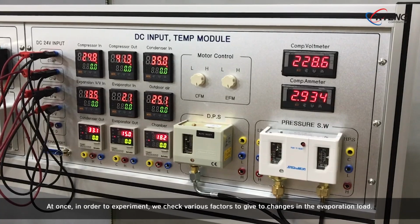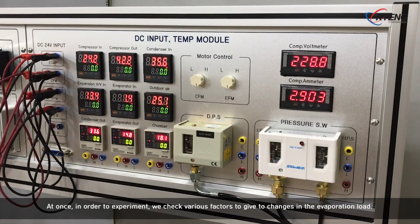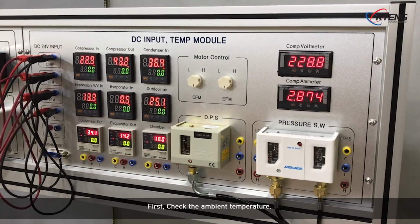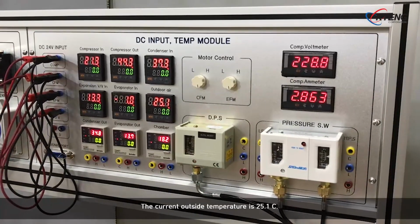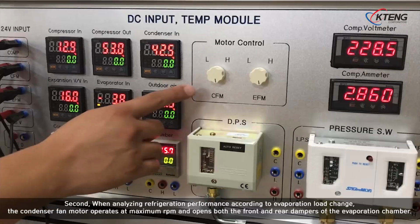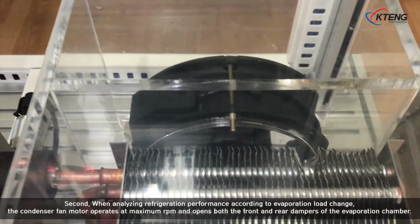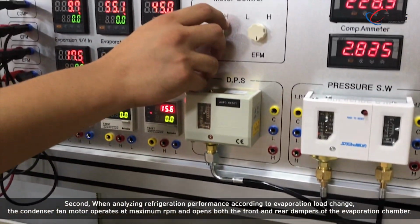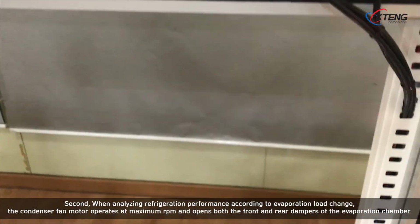At once, in order to experiment, we check various factors to give two changes in the evaporation load. First, check the ambient temperature. The current outside temperature is 25.1 degrees Celsius. Second, when analyzing refrigeration performance according to evaporation load change, the condenser fan motor operates at maximum RPM and opens both the front and rear dampers of the evaporation chamber.